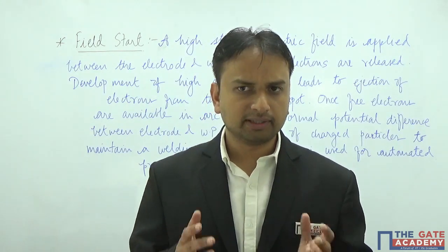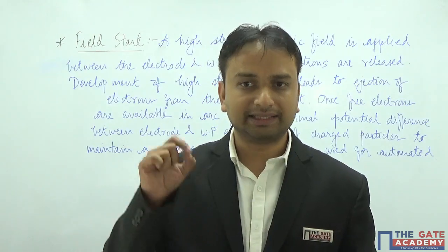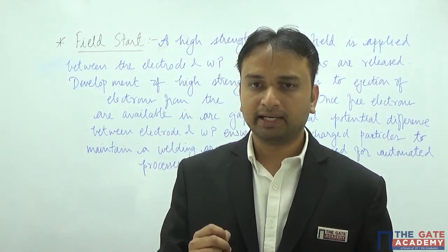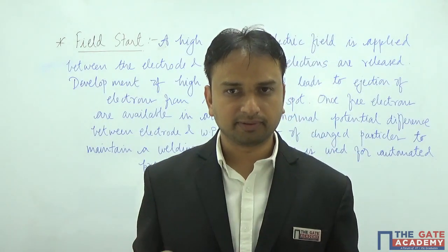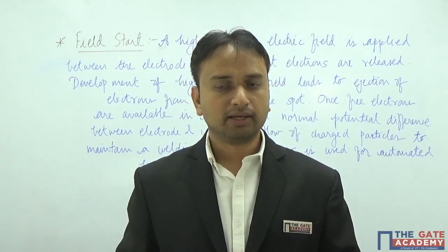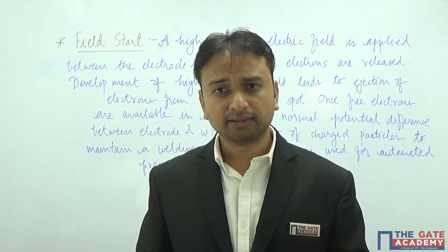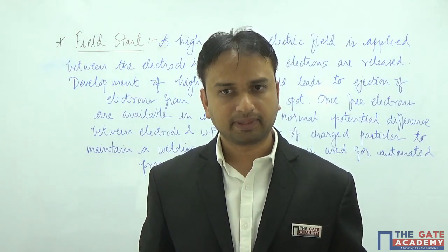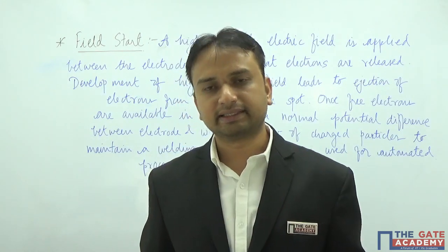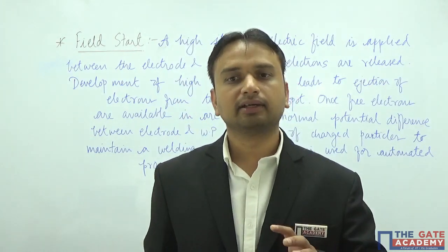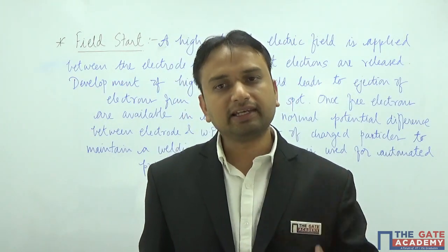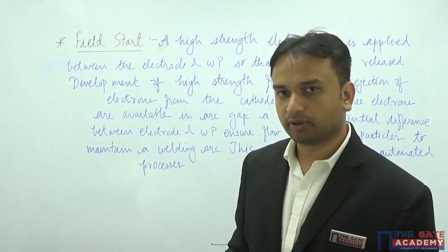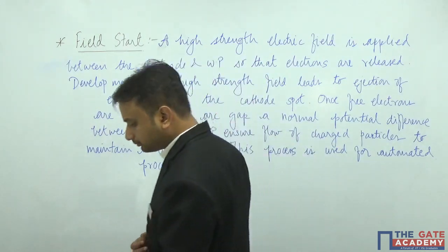So that is why, let me tell you now itself, the threshold voltage at which the ionization happens is known as the open circuit voltage. Okay, it is known as open circuit voltage. And the welding voltage is a little different. You are going to witness in the numerical problems that welding voltages are very less as compared to the open circuit voltage. I hope that you have got the point. Let us move further.